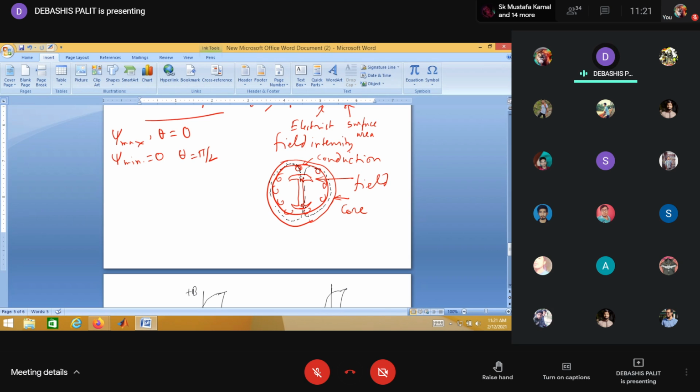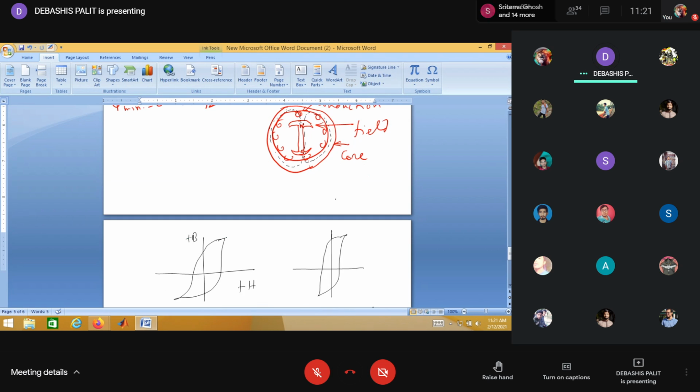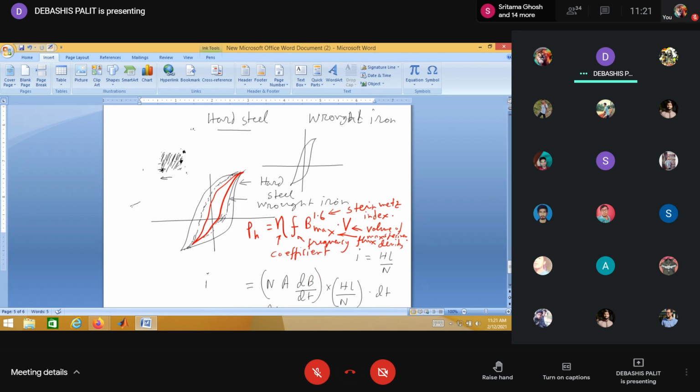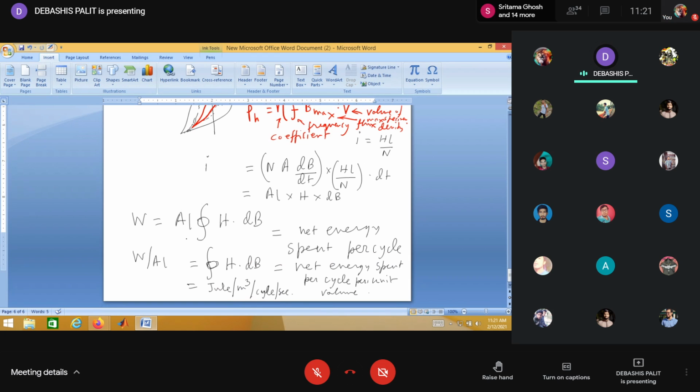This is the design principle of electrical machine design. So with maximum flux linkage, the torque per unit weight ratio of the machine is more, and then more compact, lighter weight electrical motors are designed.